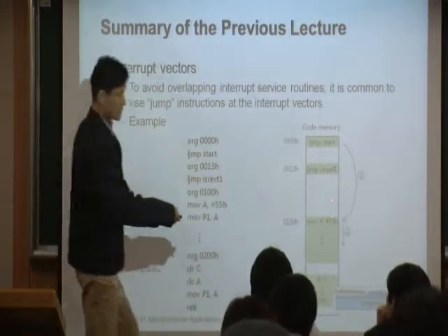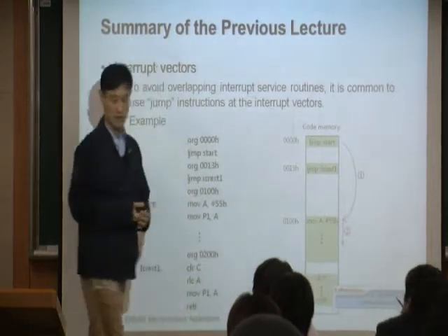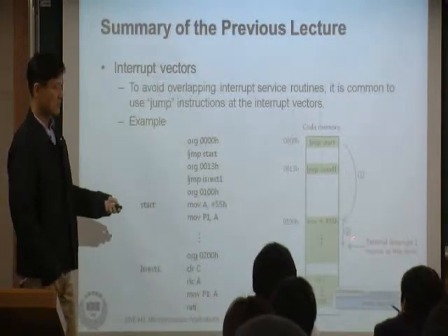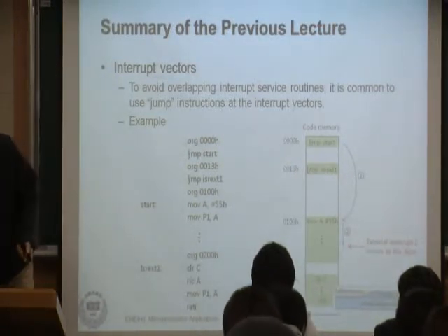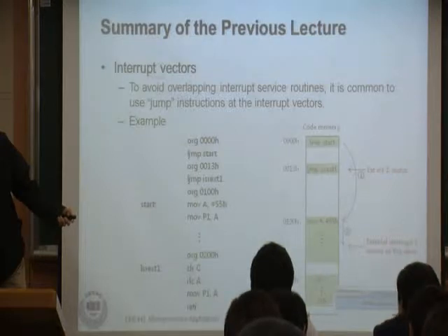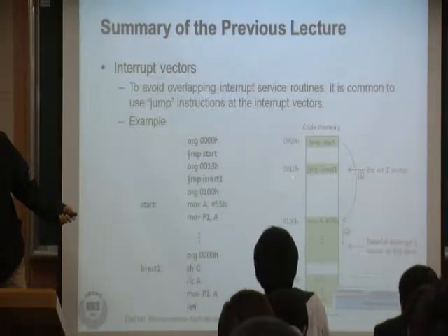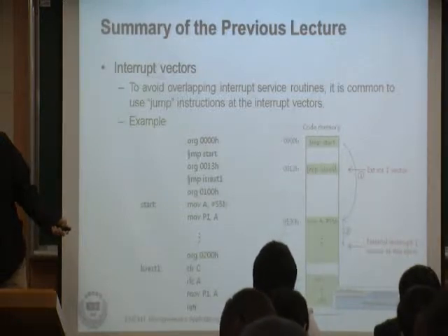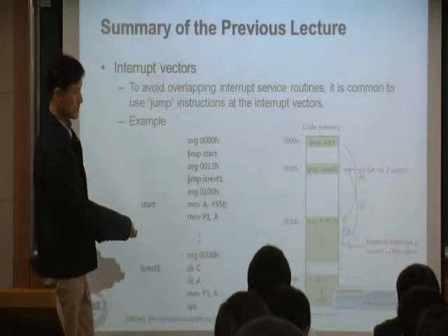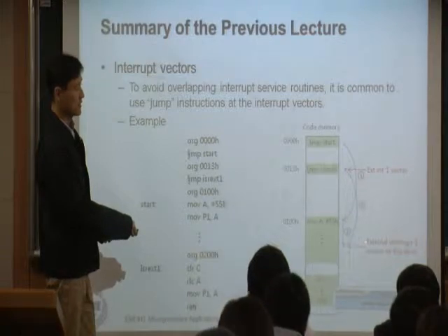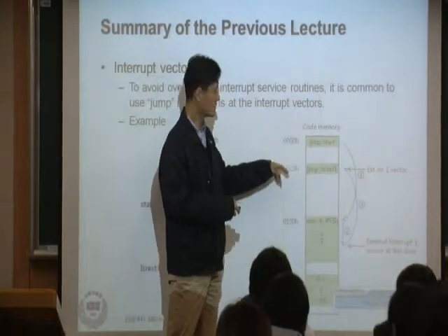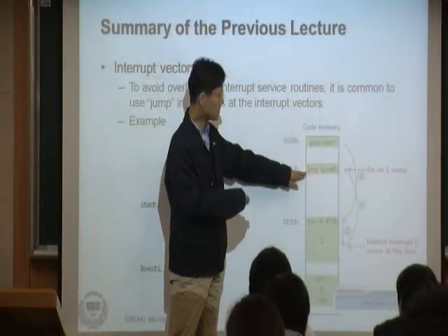Like this, right? So while you are executing your program, suddenly, unexpectedly, you get external interrupt 1 at some random time. Once that happens, based on this interrupt vector, this is a reserved, known location of the interrupt vector for external interrupt 1. So you are going to jump to there. So this is where to jump. While you are running the program, suddenly external interrupt 1 happens, so you're going to jump to there. But here we already programmed a long jump ISR external 1.